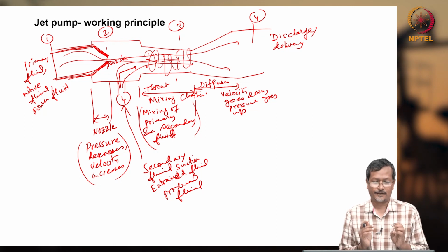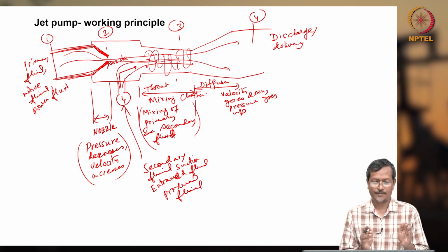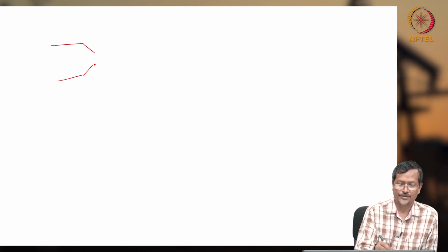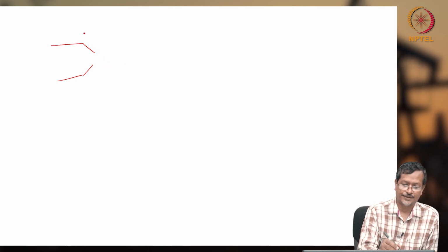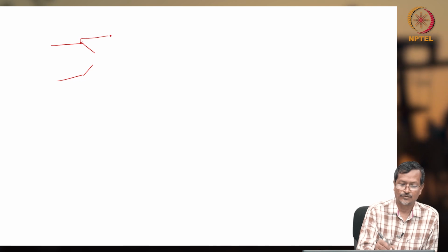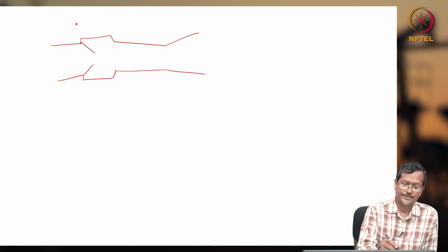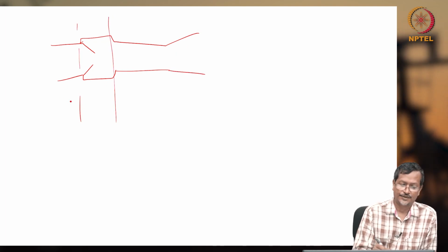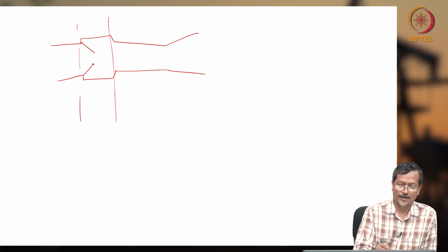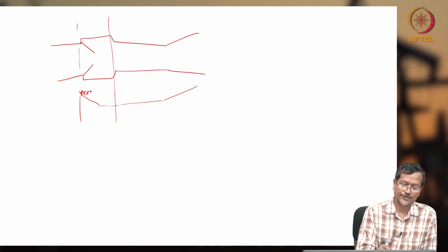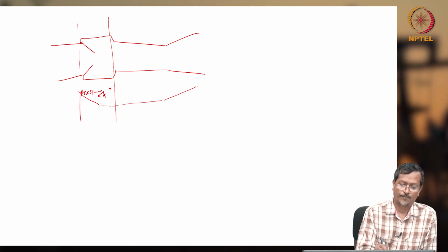Okay, now how the pressure and flow rate are changing in the nozzle actually. Straight nozzle is here. Now the fluid is going through one mixing chamber. Then what happens if I take different sections? So fluid velocity increases, pressure is going down here, then pressure will be almost fixed, then again pressure will be building up. Okay, this is pressure of power fluid.